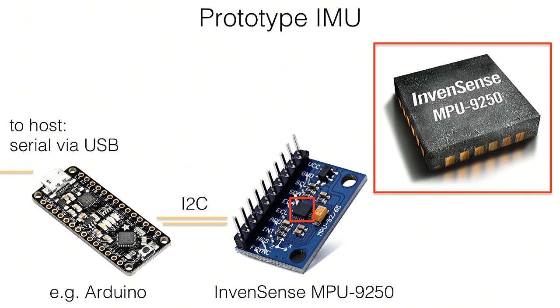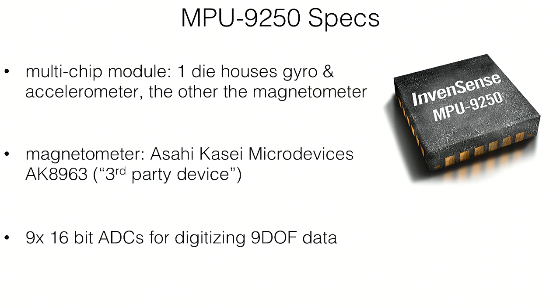But you can connect the IMU with just 2 wires, basically, in addition to power and ground. And these IMUs usually come with a breakout board, so you don't need to do much. You just plug a cable in, and it just runs out of the box. So it couldn't be simpler than that. And then from your computer, you can just plug a USB cable into the Arduino and stream out the values through the USB port, through the serial port.